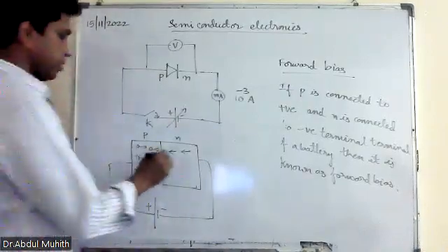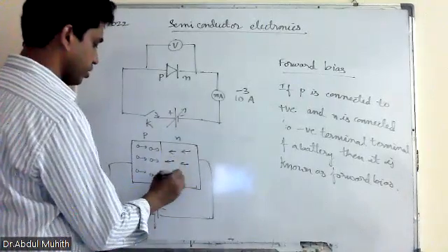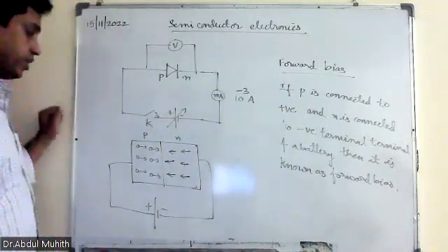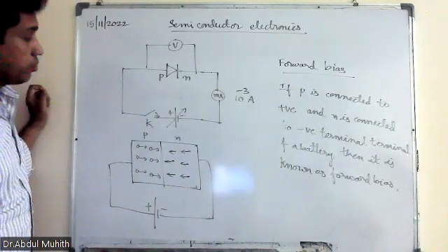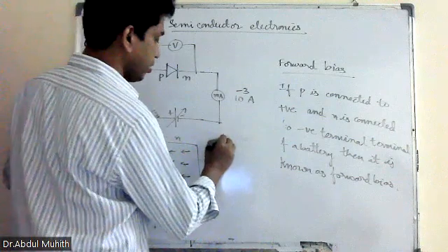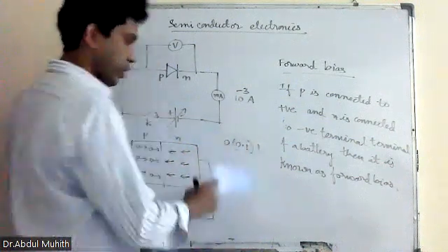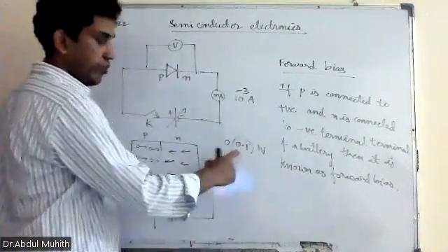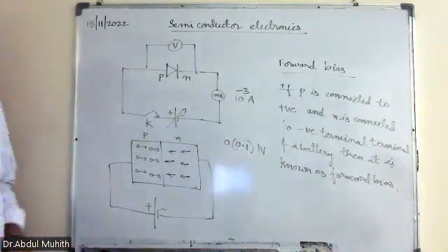So here this is an N type. Is that clear now? So this is an electron. Electrons start moving from N to P, and holes start moving from P to N. Is that clear? So this is about the forward bias. How will be the variation? In forward bias, 0, 0.1 to 1 means you start with 0. The last voltage will be 1 volt with a variation of 0.1. Means the increment value is 0.1. You cannot go beyond 1 volt in forward bias.